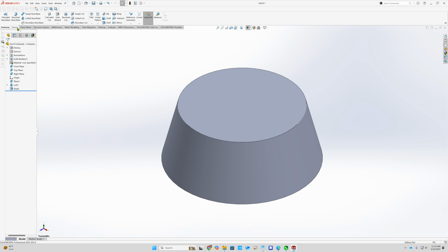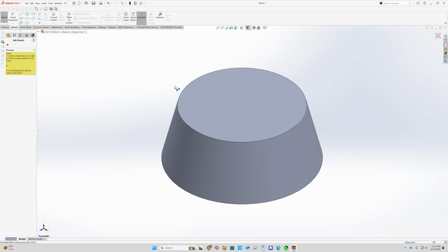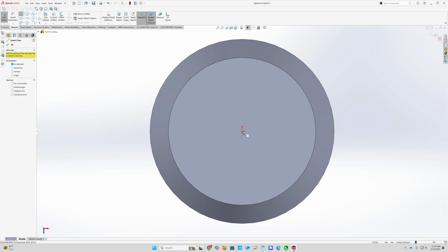I'm going to make another sketch with a line on the top here, and I'm going to go from the middle to the middle point, constrained. I'm going to make sure it's construction only. And I'm going to go from here over to here, make sure it's construction. Then I'm going to go from here up to here. Okay, make sure it's construction. Then I'm going to do a mouse gesture, which is right click and slide sideways a little bit. Mouse gesture is pretty cool.